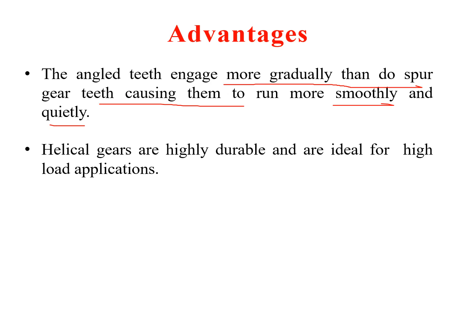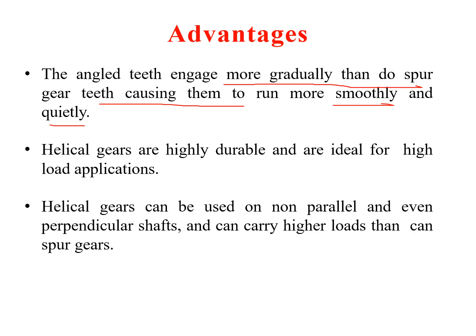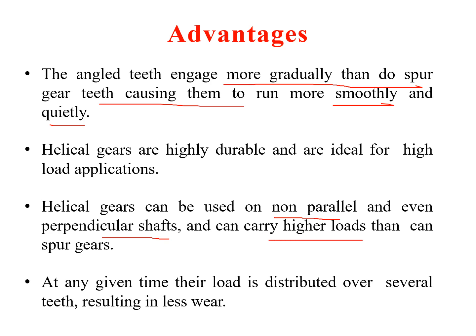Helical gears are highly durable and are ideal for high load applications. They can be used for non-parallel and even for perpendicular shafts. So it does not have the limitation of parallel shafts. And also they can carry higher loads. Next, at any given time, their load is distributed over several teeth, so it results in less wear. So load distribution is more uniform as compared to spur.